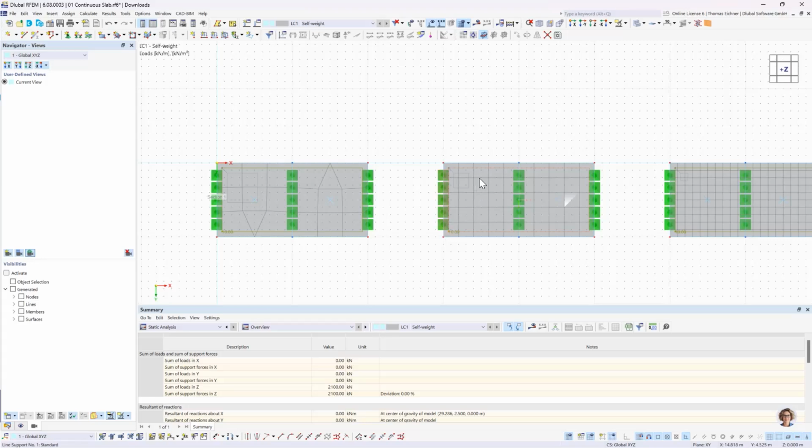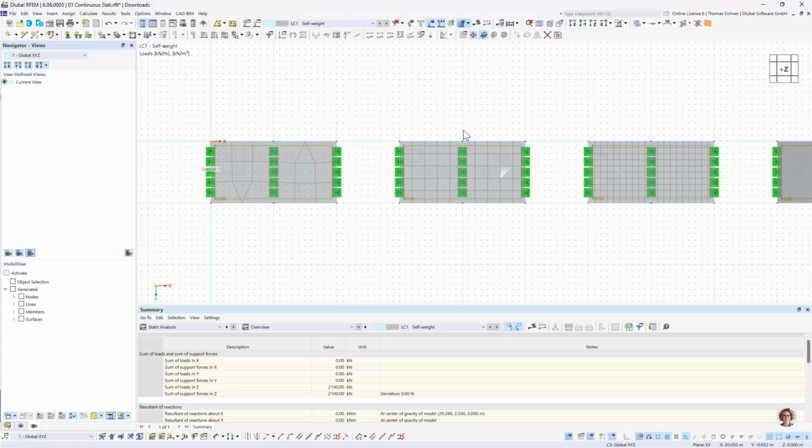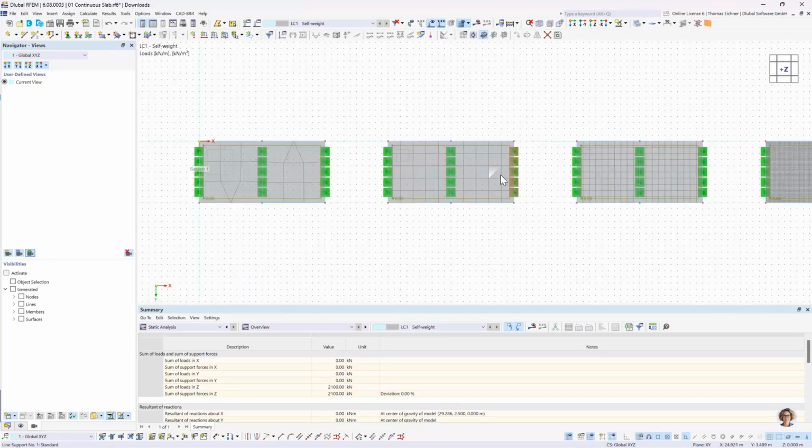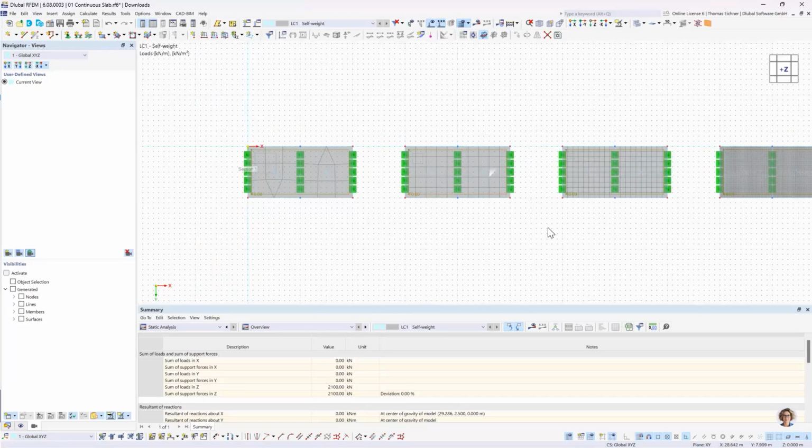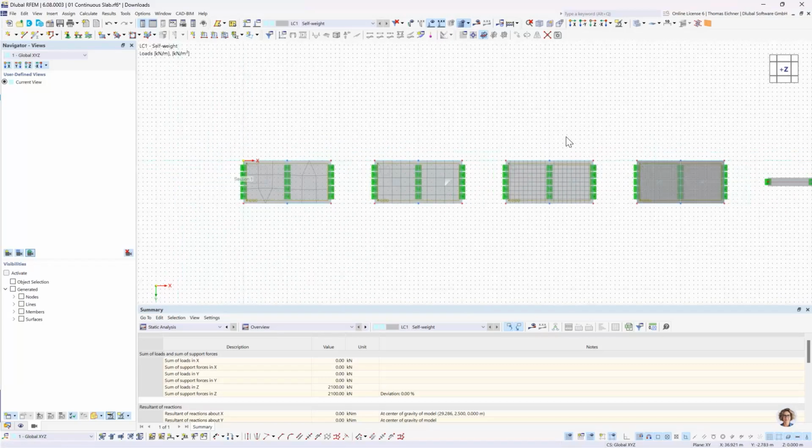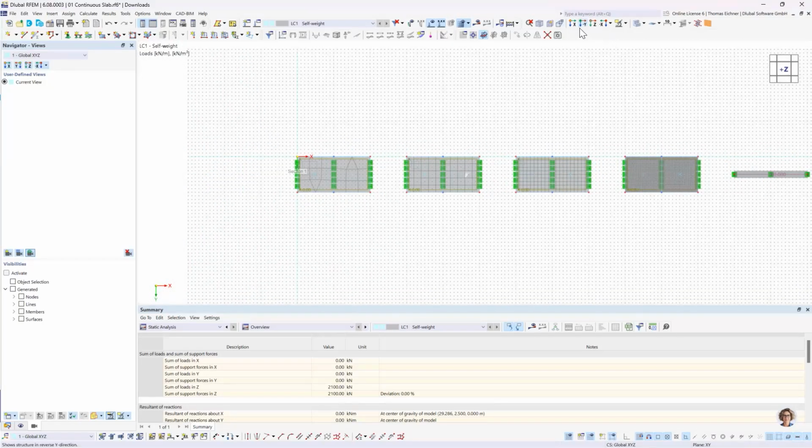Like everything, if there's a change in the boundary conditions or the force, there should be around about 6 elements to the next change. For design, if you're just interested in looking at the forces that will get to your supports, then it could also be that just 4 elements are enough. But if you wanna remember something for the future, I would go for 6 elements. Okay, then let's look at the results again.